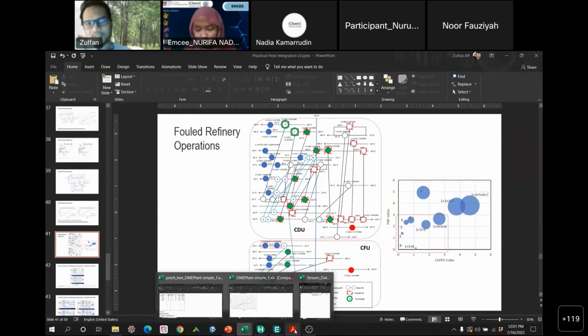If not, there is a mass balance. You know the delta T in and out of the heat exchangers. That means you know how much heat is being transferred from one stream to the other. And then based on the delta T, you can calculate the current U value, and then you compare that current U value with the design U value. So that's one way. And then you can make a plot. I will show the plot. But then people in practice, if they don't see it, regularly they will do a turnaround.